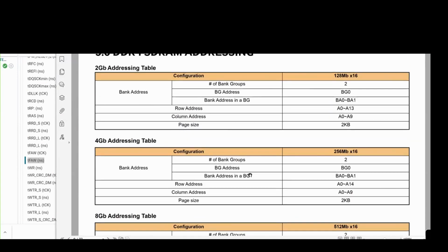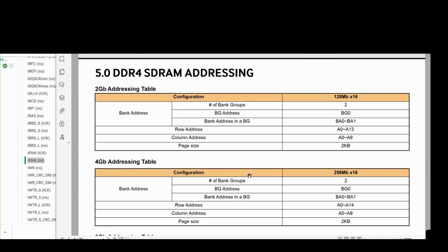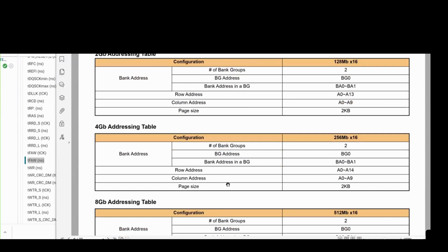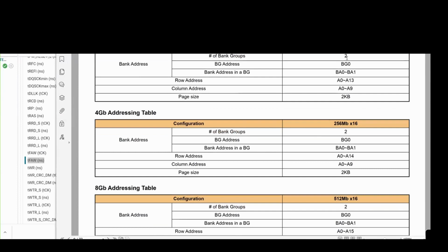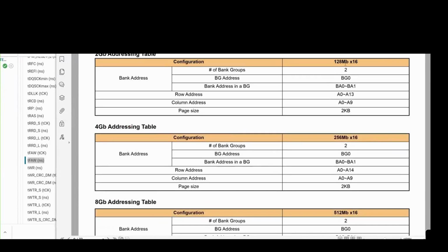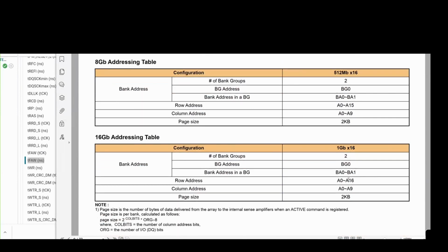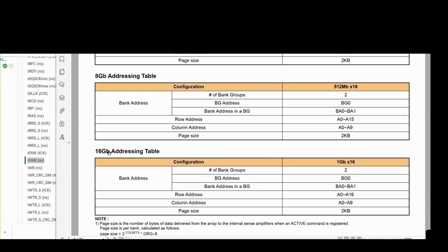That you would find typically at the top. So this is where you would determine which type of device you have. Depending on size, you could have 100 megabit, 128 megabit, 256 megabit, and so on. You can see the page size here. The page size in this case would be 2K bytes. I think it is the 2K bytes. It's the 16 version, 16 GB. It's this one, yes.